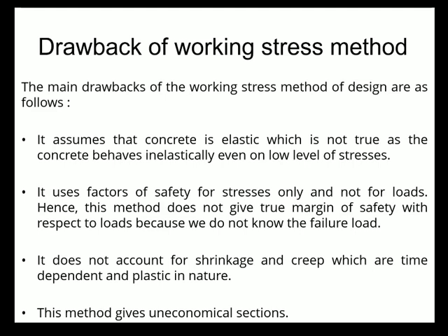So there are some drawbacks of the working stress method which were noted. Firstly, it assumes that concrete is elastic, which is not true, as concrete always behaves inelastically. Its stress strain curve is never straight. Secondly, it uses factors of safety for stresses only and not for loads. Hence, this method does not give a true margin of safety, because the load as well as the strength, everything is probabilistic. Because of this probabilistic phenomenon, we introduce the safety factors, and here it is not completely done for the loads.